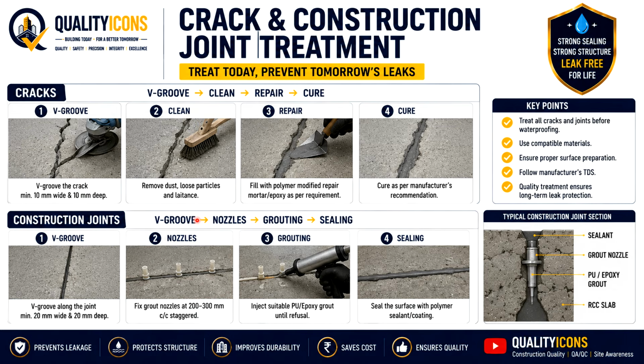See V groove cutting and cleaning, repairing. It means repairing with polymer modified repair mortar or epoxy as per your project requirement. Cure as per manufacturer's recommendations. The groove must be properly cleaned before filling with the approved repair material.